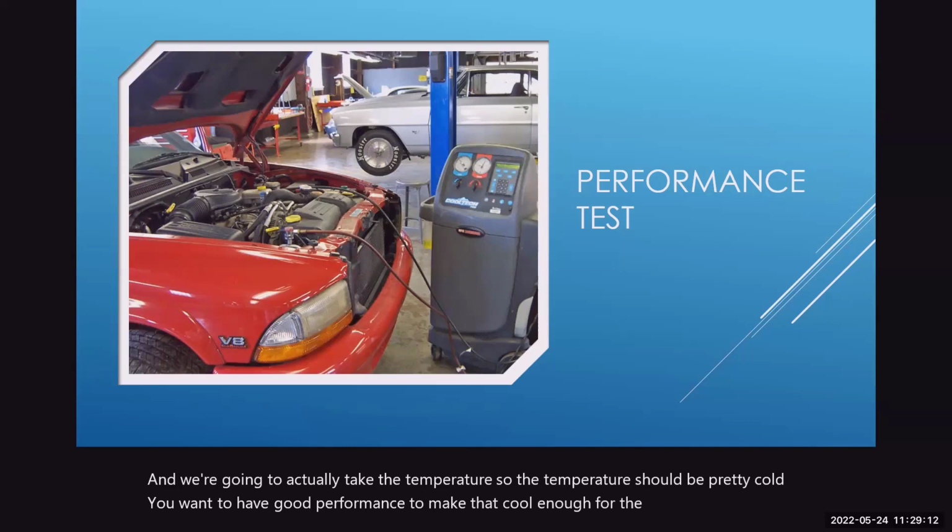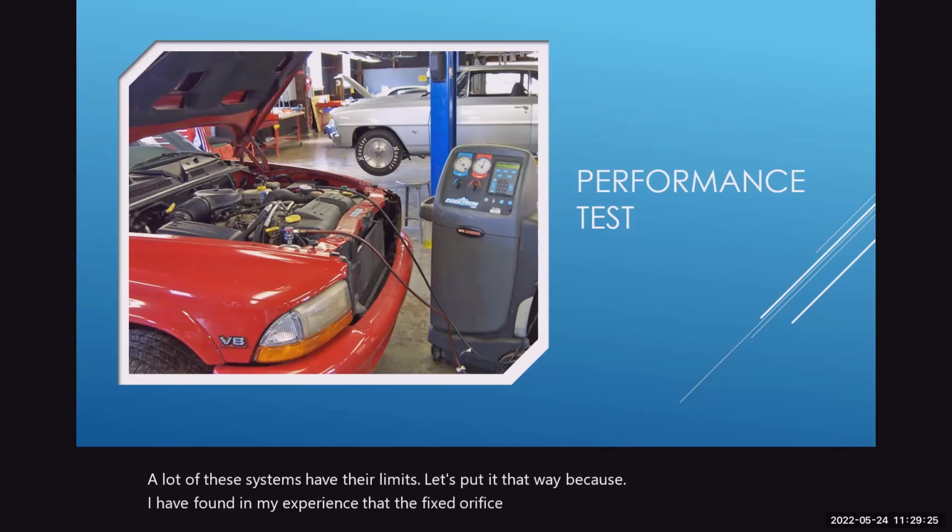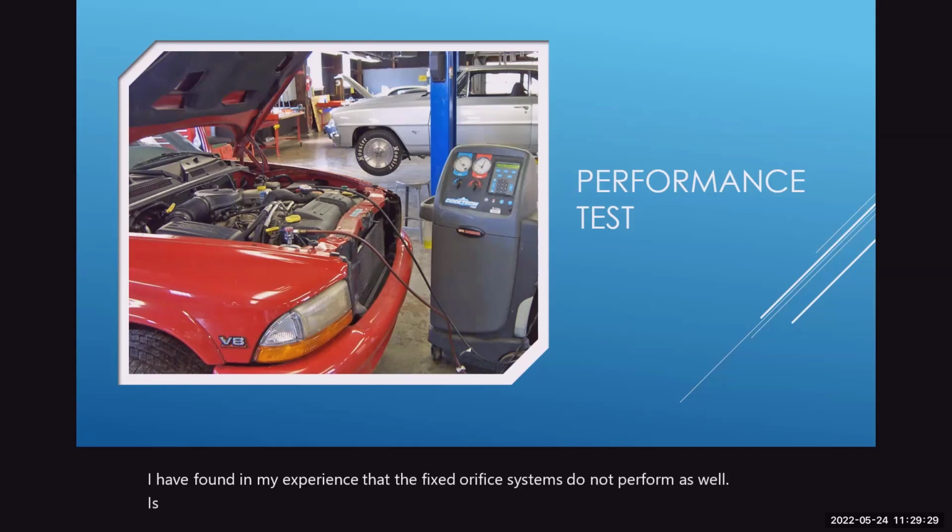Now, granted, a lot of the systems have their limits, let's put it that way, because I have found in my experience that the fixed orifice systems do not perform as well as the expansion valve systems do. So that's something to take into consideration when you're doing your actual temperature testing, your pressure testing, and stuff like that too.